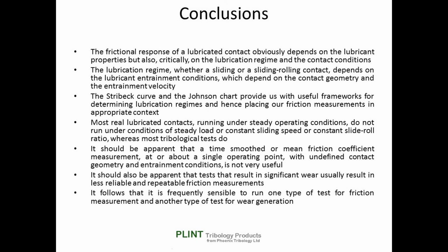The frictional response of a lubricated contact obviously depends on the lubricant properties, but also critically on the lubrication regime and the contact conditions. The lubrication regimes, whether sliding or sliding rolling contact, depend on the entrainment conditions.